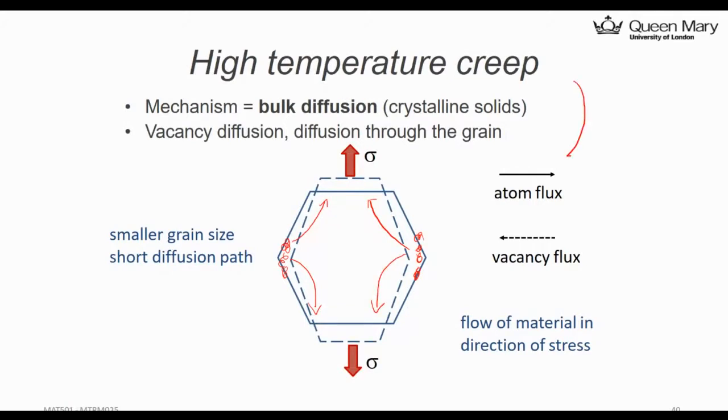If you look at your sample in tension, there's a kind of contraction, like the Poisson ratio. You can relate it to that. Transversely, it will shrink, because the material travels to that area. And what I'm plotting here, we can see eventually the atoms move to here, and that part will become an empty space, a vacancy.